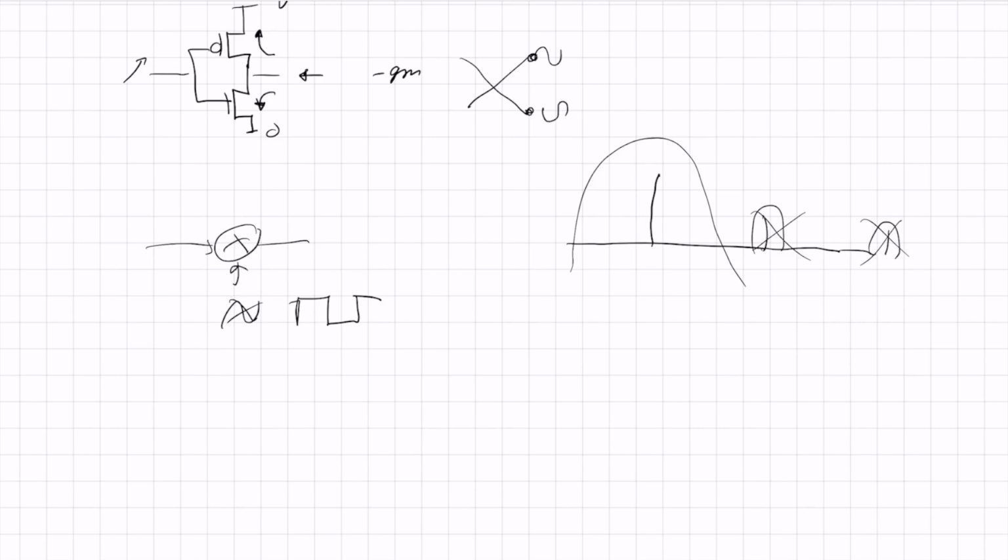And then making a multiplier with a square wave is in fact very easy. It's just a set of switches. So again, in a case of a differential signal, if I multiply with 1, I just take the wires like this. And if I multiply with -1, I just put switches so that I just cross between plus and minus. So this way I can multiply my signal with +1 or -1, and that also does down conversion.